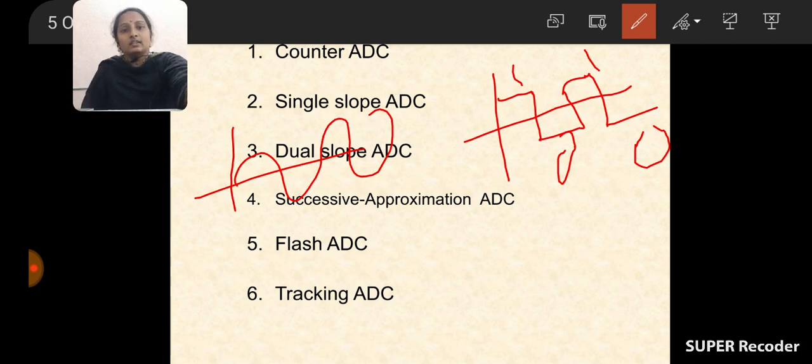But an analog signal has either continuous increment or continuous decrement. So the amplitude of an analog signal is continuously varied with the time period. But digital never varies. It has only two levels, one is high level, other is low level. Even though the time is increased, the levels are only two. The levels are not changed, high level as well as low level. Here the high level is considered as power supply and the low level is considered as ground.